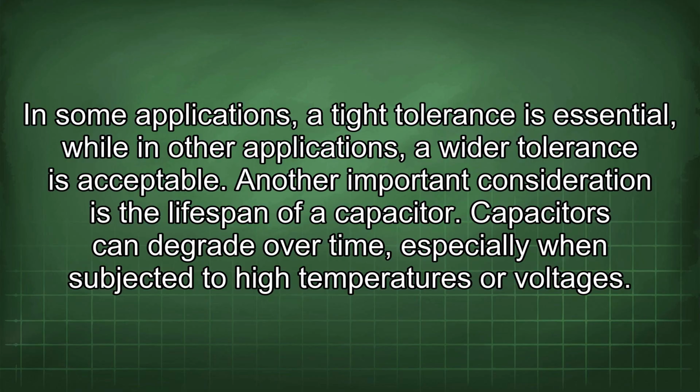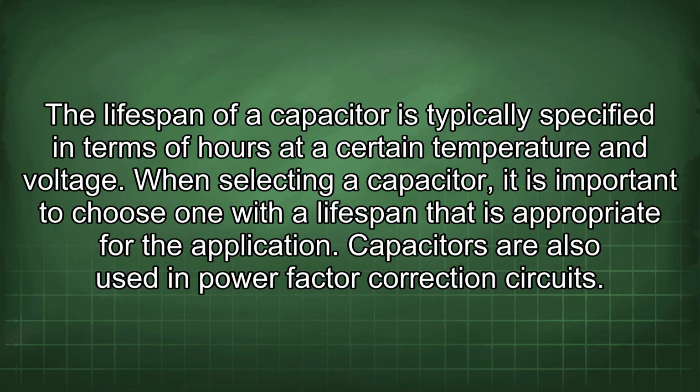Another important consideration is the lifespan of a capacitor. Capacitors can degrade over time, especially when subjected to high temperatures or voltages. The lifespan of a capacitor is typically specified in terms of hours at a certain temperature and voltage. When selecting a capacitor, it is important to choose one with a lifespan that is appropriate for the application.